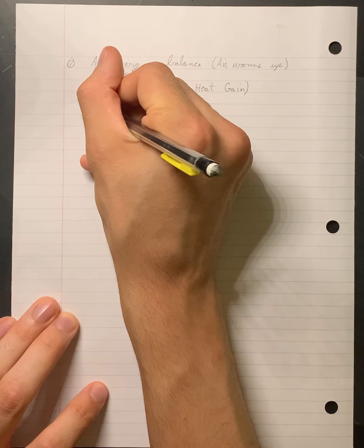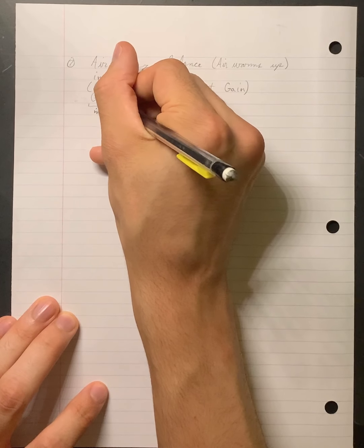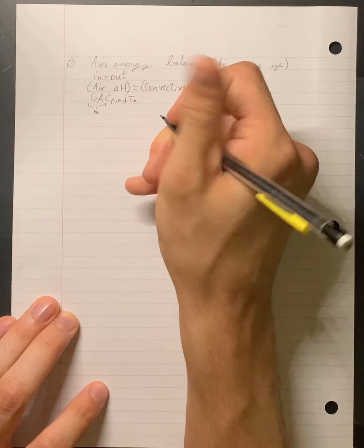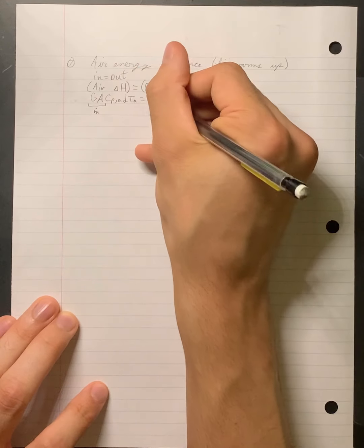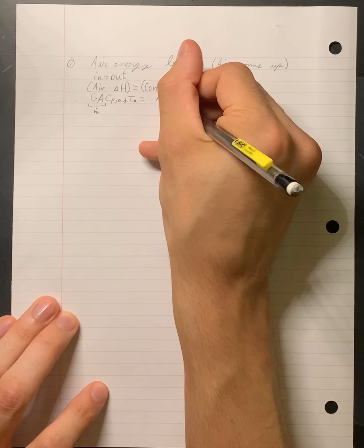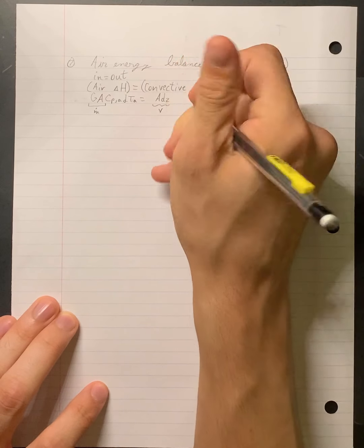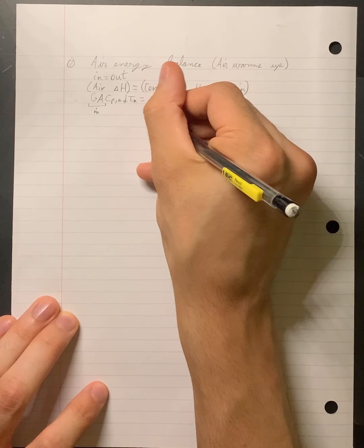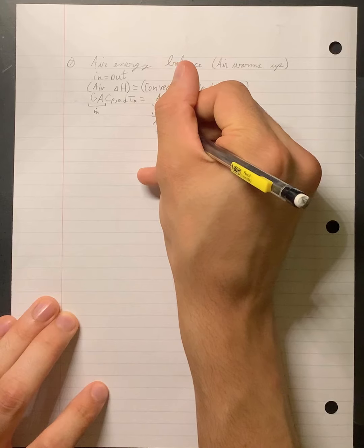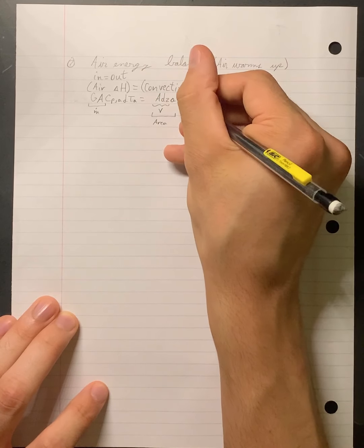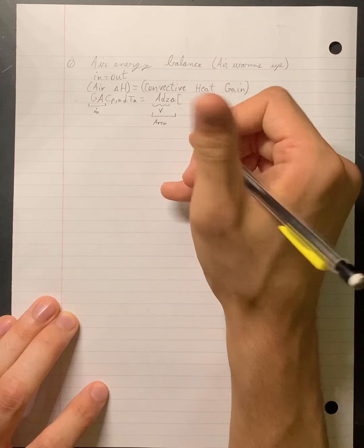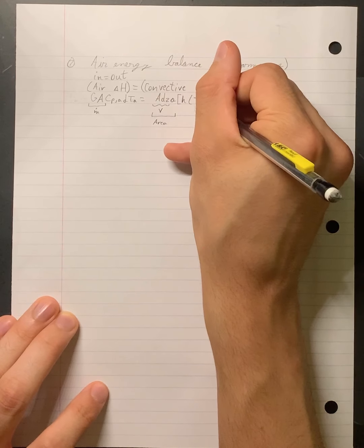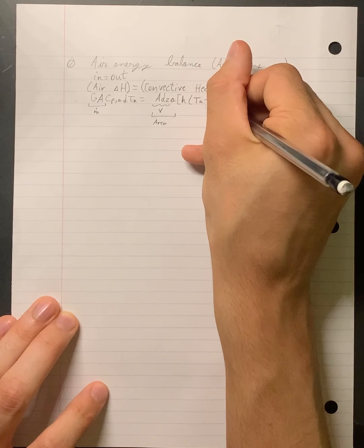This gives us basically a mass flow rate times the heat capacity of air times the differential change in temperature of air across that control volume equals A dz, which again, this is our volume just like before, times the surface area to volume conversion factor, which gives us an area, multiplied by our convective heat gain component, which would be the heat transfer coefficient times the air temperature minus the water temperature.